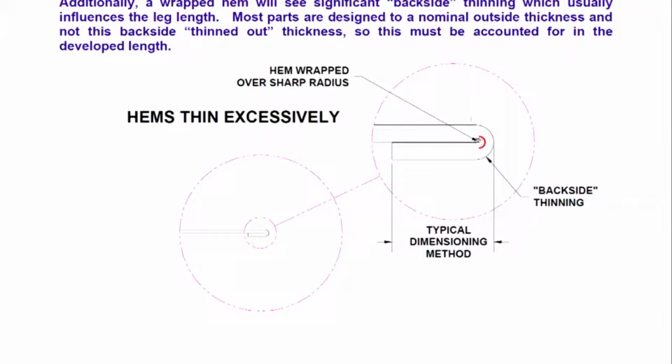So, you have a little offset here, I can't do it. And then in this portion you probably need a cut here and one more cut here to make sure that a grommet can be inserted here. In the power supply which I showed you first time, it was there. So, materials are often tried and specified also, saying can you make a 180-degree bend.